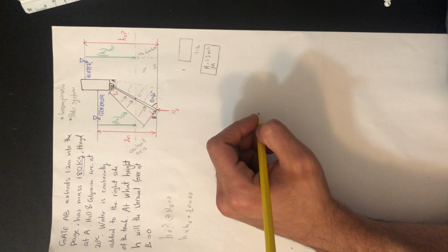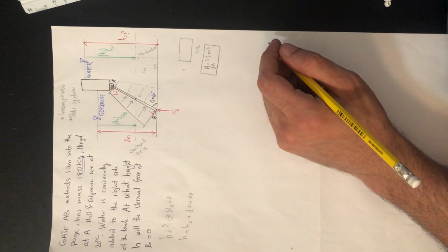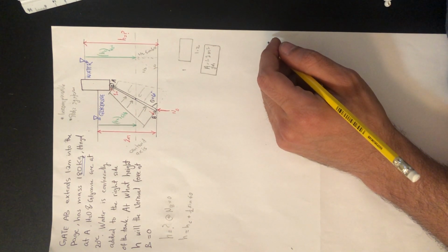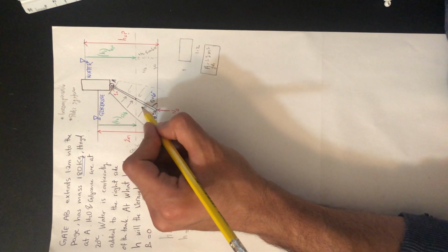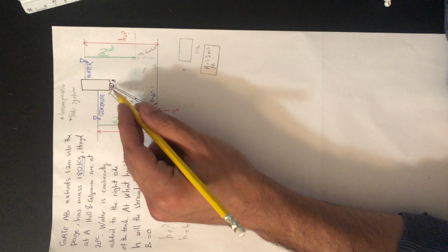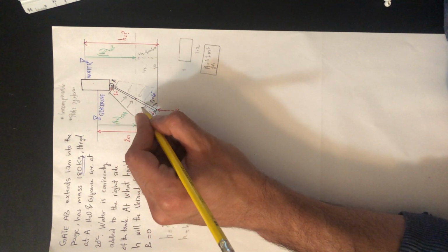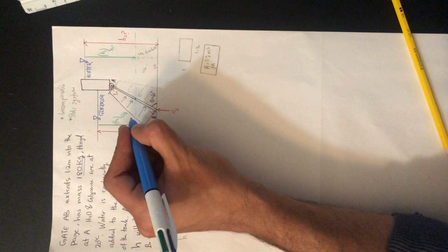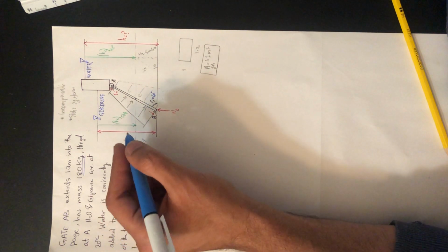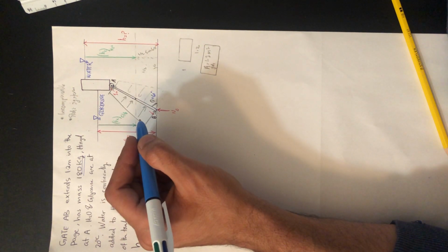So pressure and length are directly proportional. We also know that if we do the total sum of the pressure acting on this entire surface, we are going to get the resultant force. Our resultant force acts under the center axis, the centroid axis.